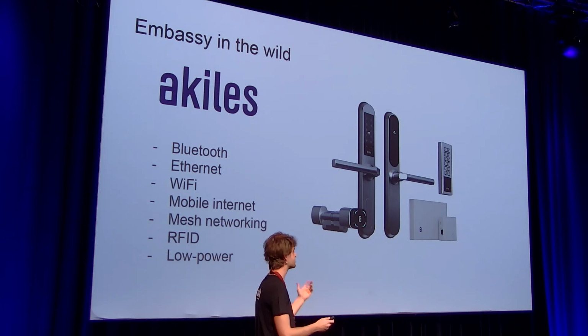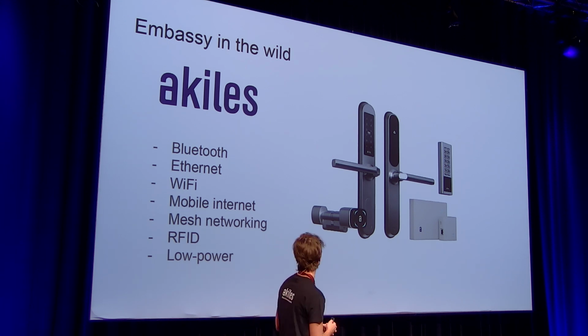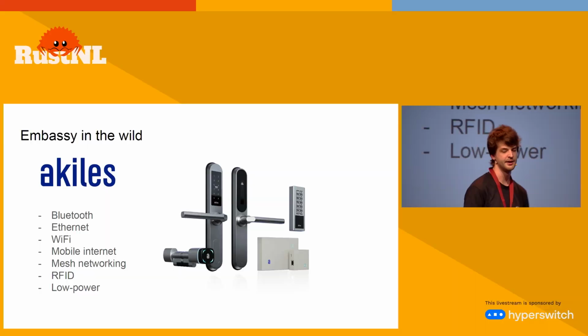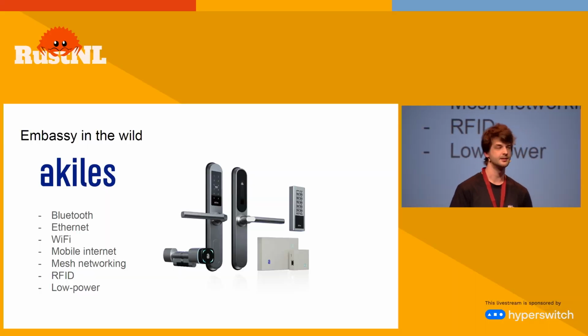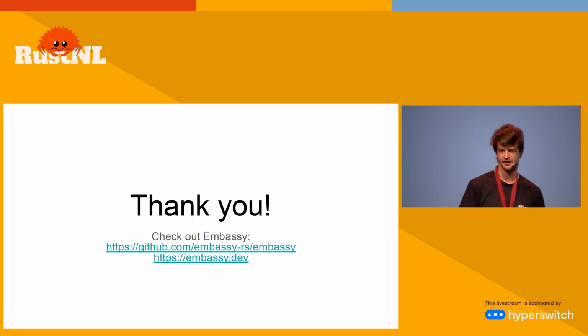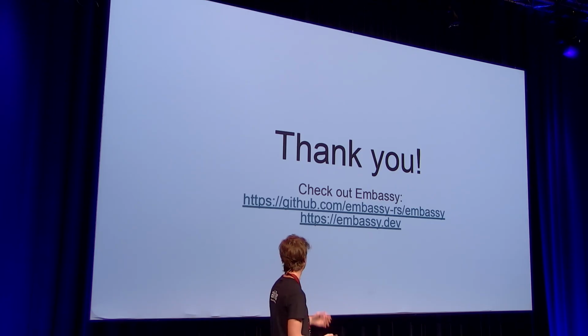So the current status is that it's mostly mature. It works really well. It has allowed us to ship really stable firmware with lots of fancy networking things: Bluetooth, Ethernet, Wi-Fi, mobile, mesh networking, and also low power. Async is really great because it gives you low power operation for free. We get battery powered devices where the battery lasts for one year without having to do any special things in your code. Just yield and wait, and the executor automatically puts the core to sleep, and you get the best power consumption possible.